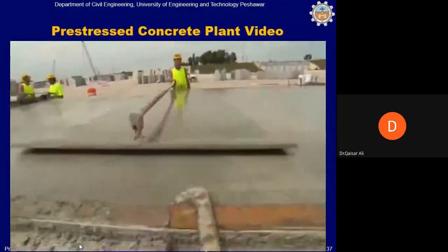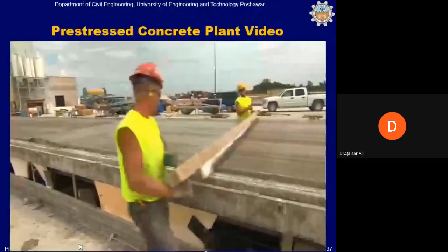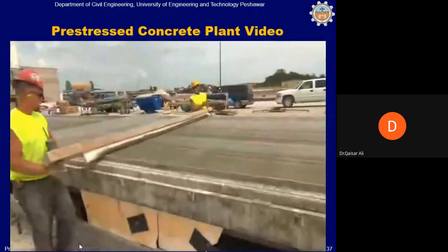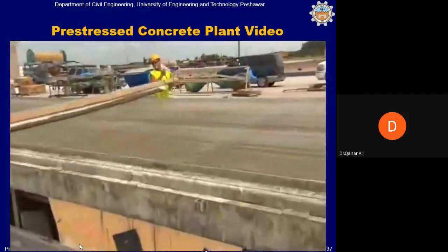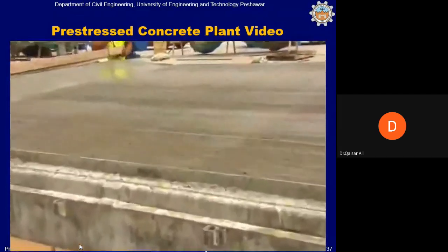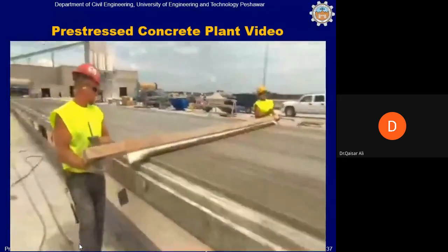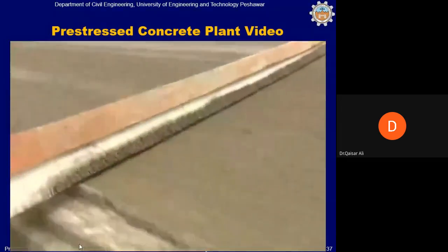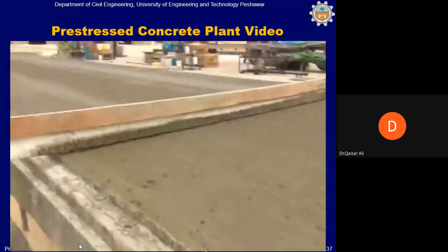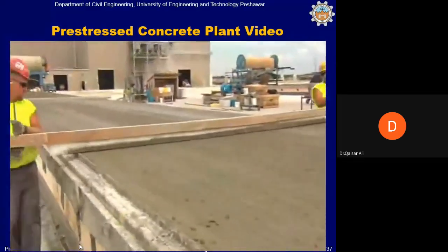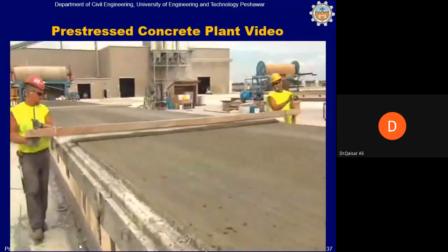If a cast-in-place topping is necessary, the surface will be made very rough so that a good bond will be achieved. If it is a roof, the finish will be relatively smooth, but not necessarily perfect. In this case, the surface is broomed as these double Ts are being used in a parking structure. Different patterns can be applied depending on the needs of the project.